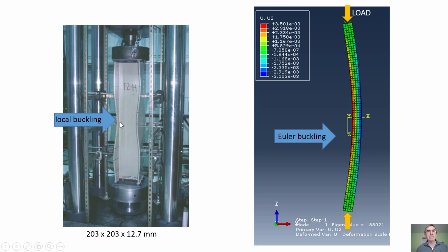The local buckling load can be predicted accurately, or testing can be done to obtain it. And it is pretty much independent of the length, or properly the slenderness, of the column within some range. We're going to talk about that.